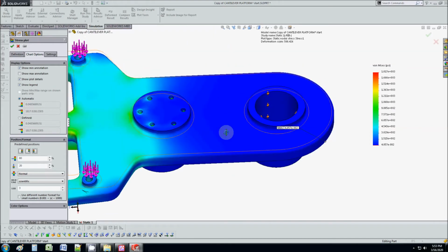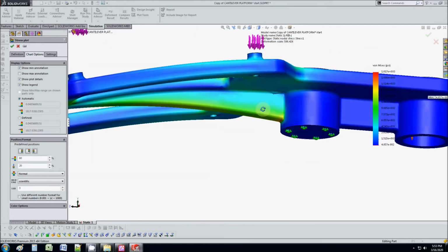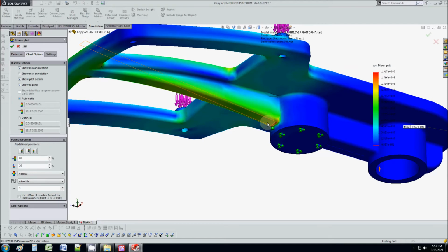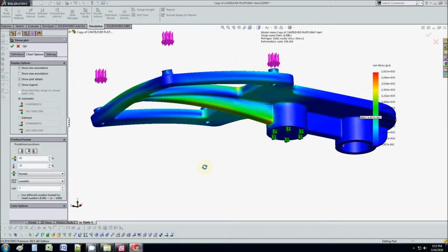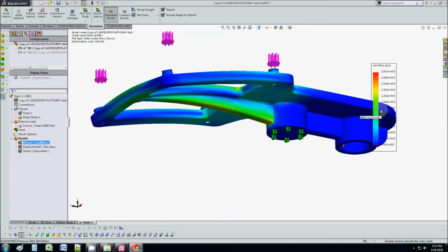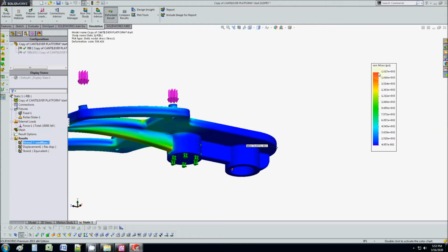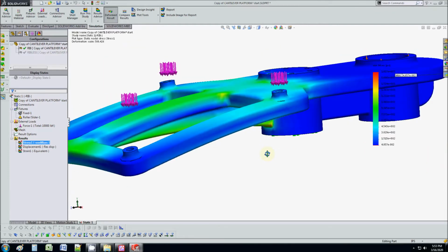You say, all right, I'm going to put an I-beam here. I don't even need material here. It's a waste of metal. Whereas here you may want to beef up that rib or maybe add another one to the side. Okay, so that's what you do. You know, when you're optimizing, you design, you iterate, you optimize, and you do that over and over again. Okay. So that's what this rainbow meter means. The red is the largest number, and then the blue is the lowest number, and then you try to find it on the diagram.